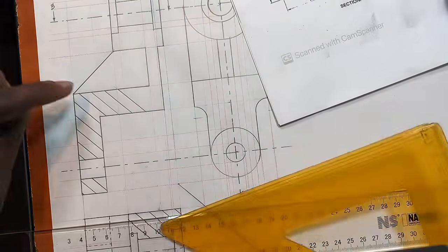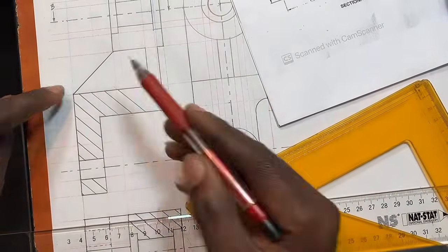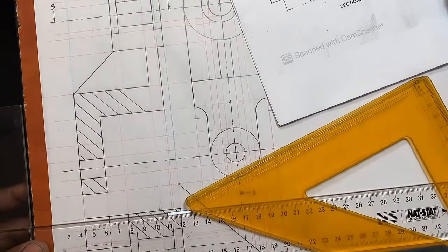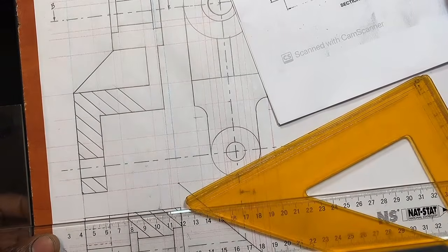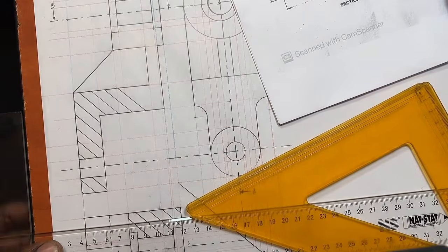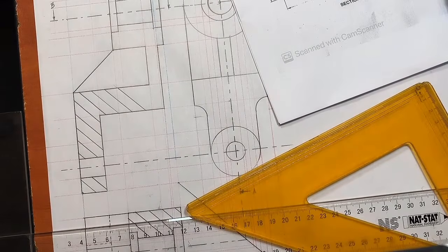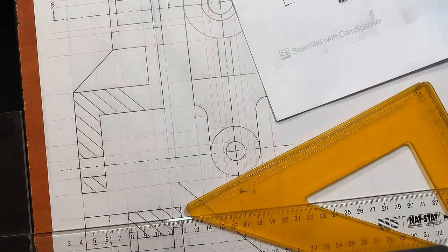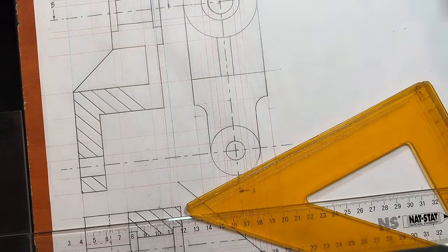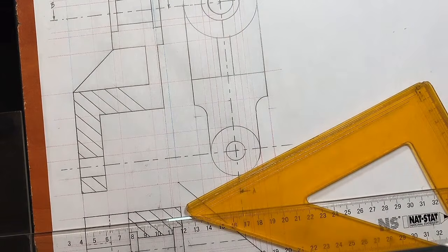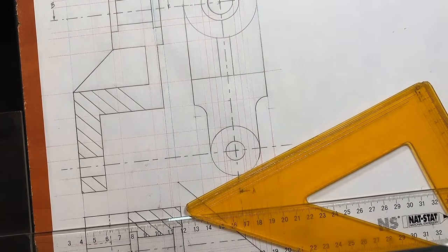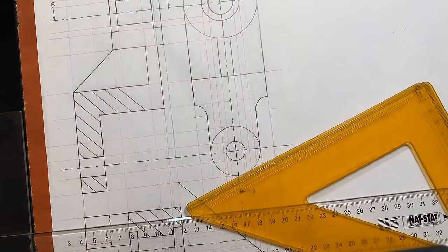You rather section in a wrong place, but not on top of a solid line. You understand? When we mark, we check such kind of understanding, that a student understands that we rely on keywords before we even check the hatches. Is it correctly sectioned? You understand? We check those strong points to say that this learner understood the protocol or the way you approach your section. You understand? We don't section on top of a solid line. We do not section on top of a chain line.